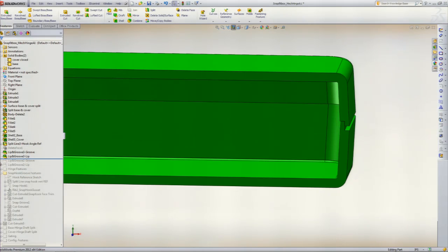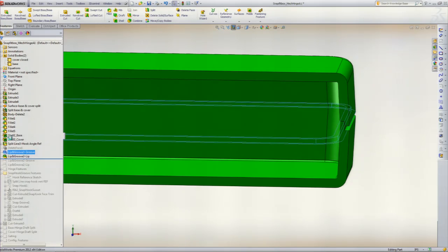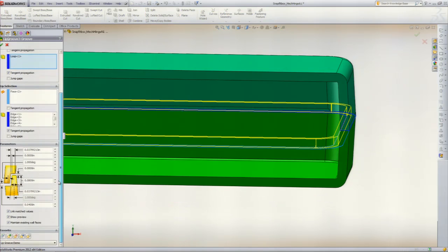So what you can do is, like I have here, depending on my wall thicknesses, here at the bottom where it says favorite, I have different favorite lip and grooves for 100 thousandths wall, 78 thousandths, 60 thousandths walls. So I just have to bring those up, and I don't have to recreate those each time that I need the reveal. Any questions on this?